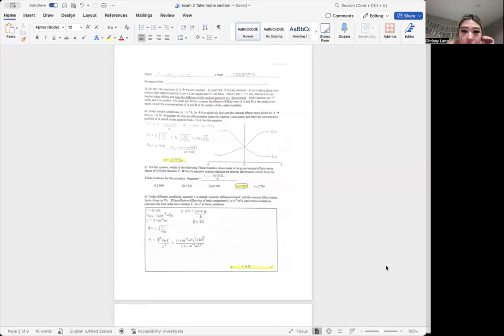So first we're going to go over question 3, where we're looking at the two different first order reactions, A to B and R to S, both happening inside the same catalyst. The slab is very thin, it's just 0.1 centimeters thick compared to the surface dimensions of 2 centimeters by 2 centimeters. So you would want to treat diffusion as one-dimensional across the thickness and ignore the edge effects.